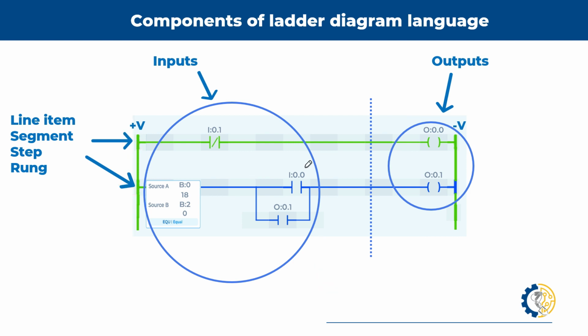Okay, so perfect. Now, as elements or instructions for programming, all of these instructions, and also these steps, generally everything that we see here on our left are permissions. And if they're permissions, they're inputs. For example, this denied contact is a permission. It can also be a push button. This is a normally open contact. It is an input, and it can also be a push button or a pulse. Even though this is an output, to direct it to this output we're using an input. So this is also on our input side.